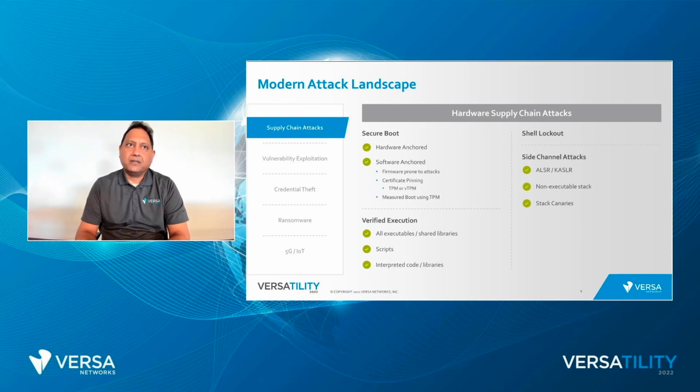But if the root of trust is not anchored within the hardware, then that software anchored root of trust can be tampered with. So the attacker can potentially replace the certificate that is used to verify the software root of trust, and they can actually replace the firmware, and such kind of attacks are possible.